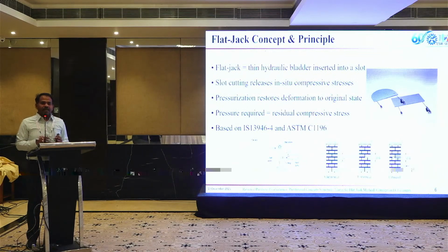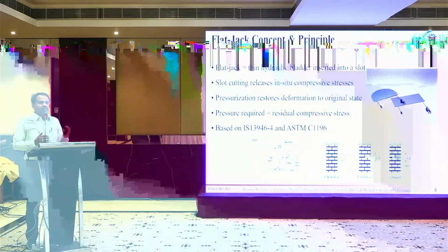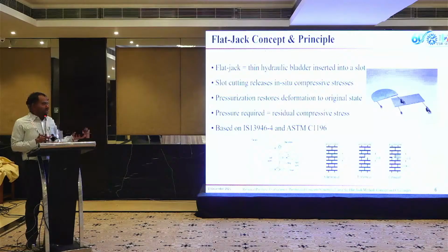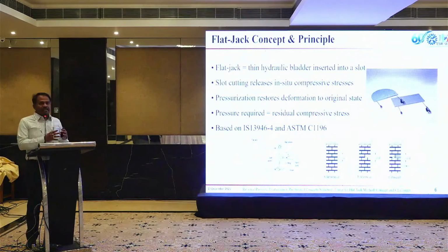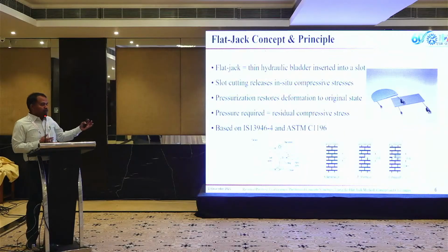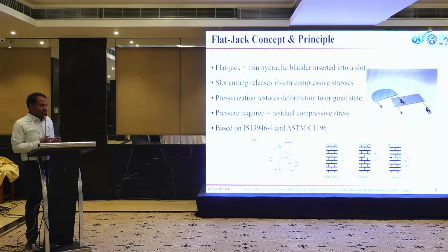Flat jack method is an old technique which is extensively used for measuring the in situ stress in masonry structures or rock mechanics. What it tells is that the masonry structures have a compressive stress which is inbuilt because of their own weight. So these techniques can be used to identify the existing stresses in the concrete.